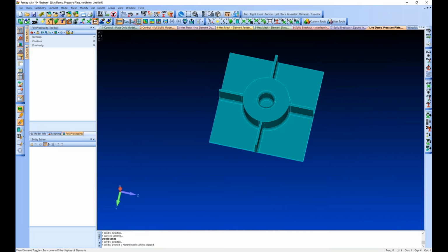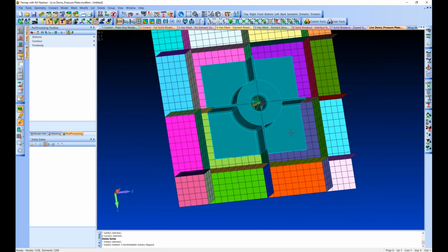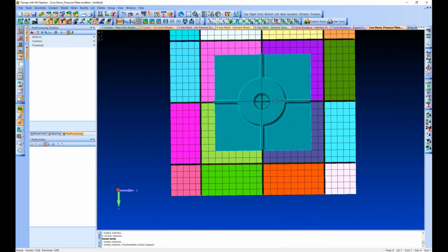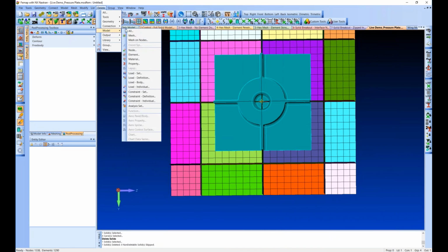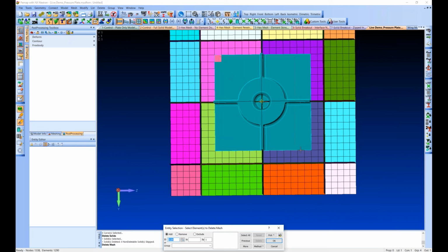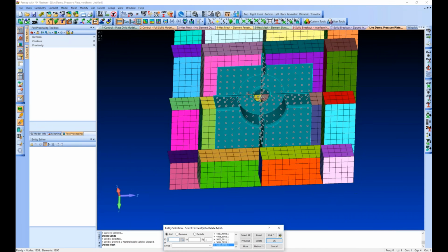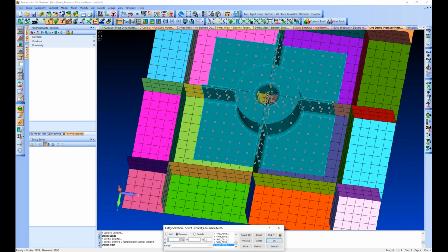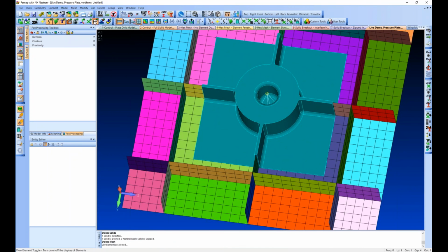All right. And the same is true with this plate mesh in the middle. I'm going to mesh this solid, so I don't need these plate meshes anymore, so I'll just delete those. All right. So you want to keep your interfaces. It's just going to be easier as far as speed and everything not to have to redo these. So we'll keep them, we'll address them later. We're just going to delete this mesh.